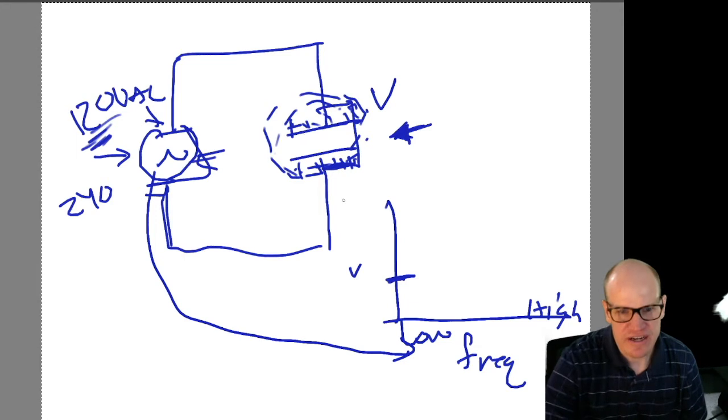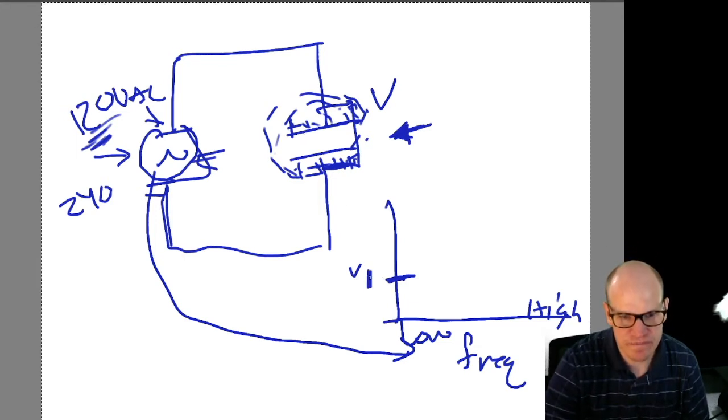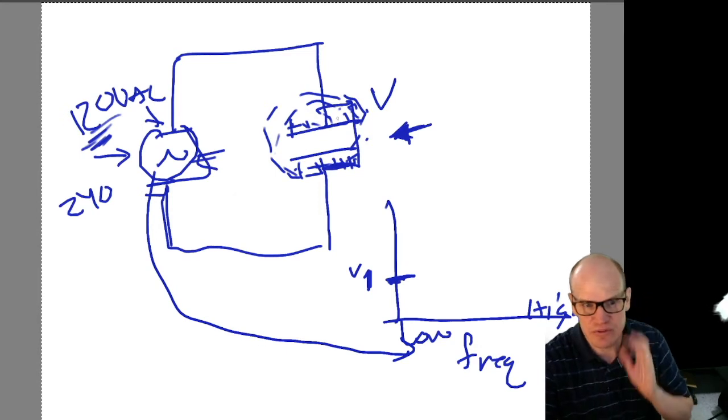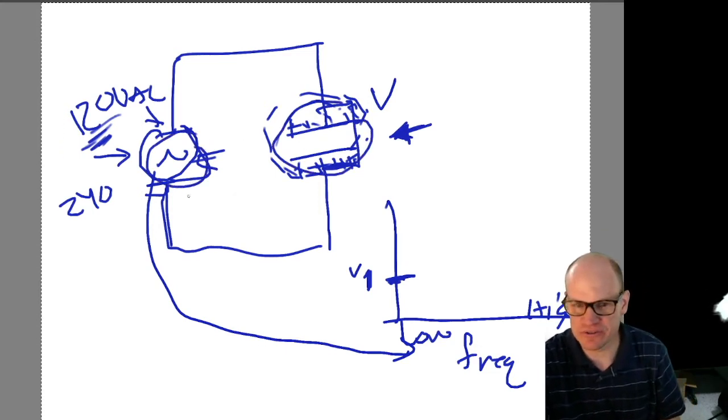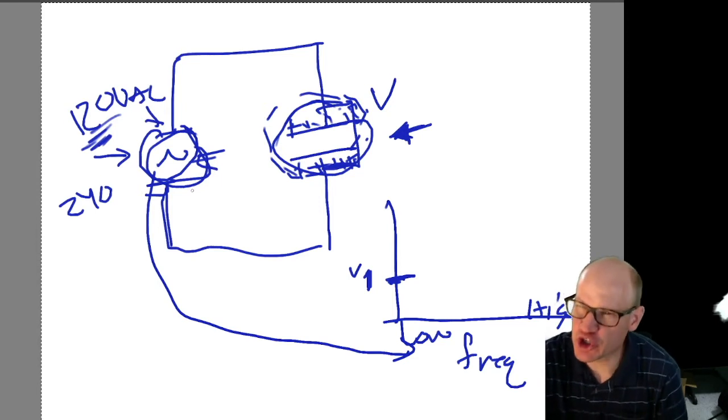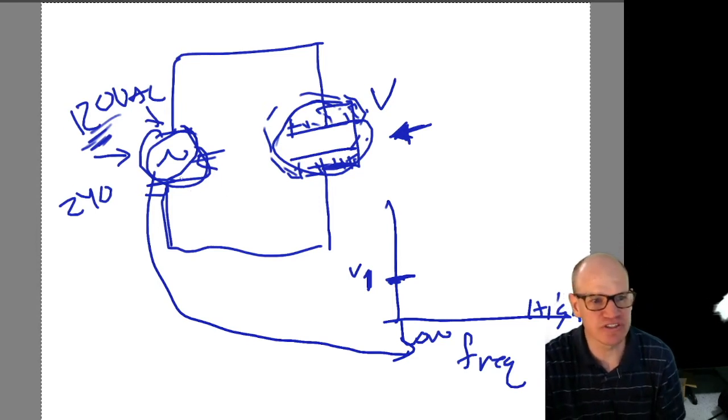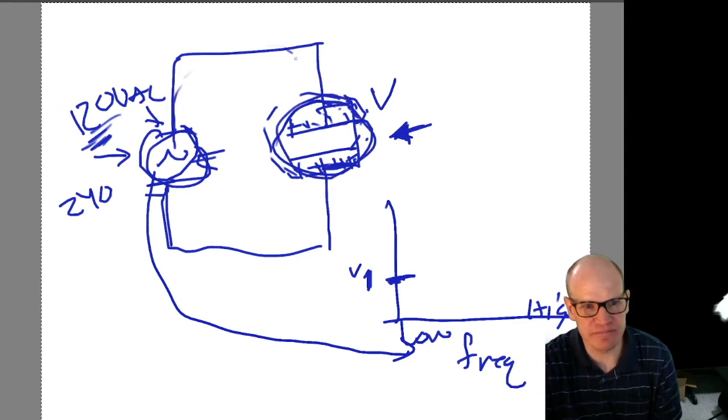Okay, so anyways, here, this is a 1, this is 1. So when you're operating at low frequencies, the response on the capacitor is exactly equal to the response from your power supply. At super high frequencies, what's going to happen? At very high frequencies, this acts like a short because it never has time to build up any charge. So like charges will start flowing, okay?